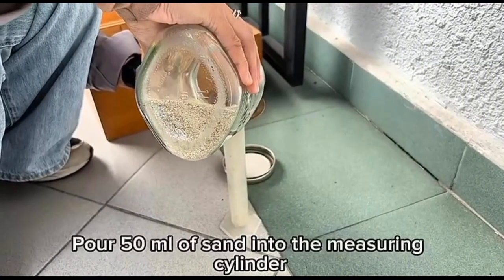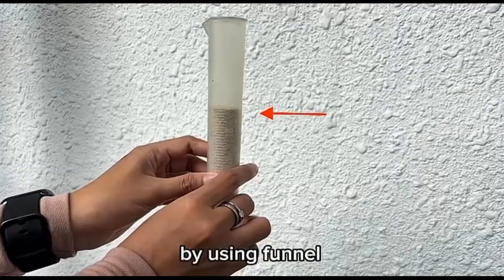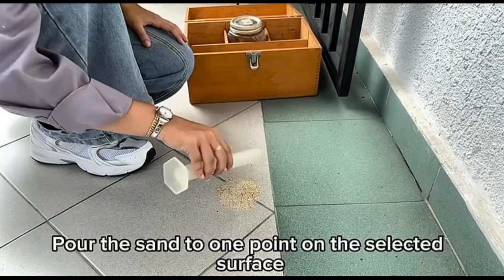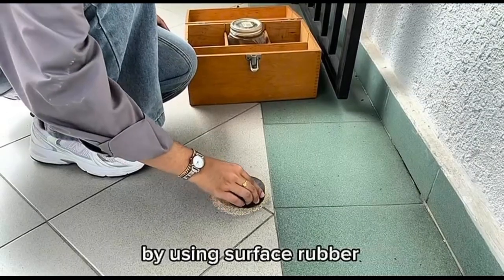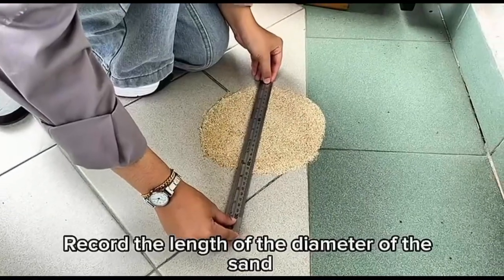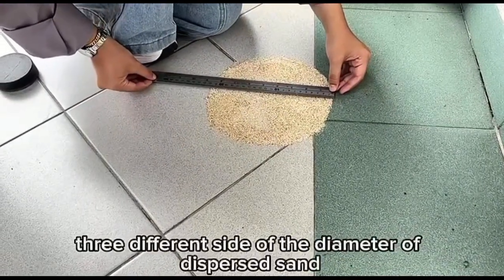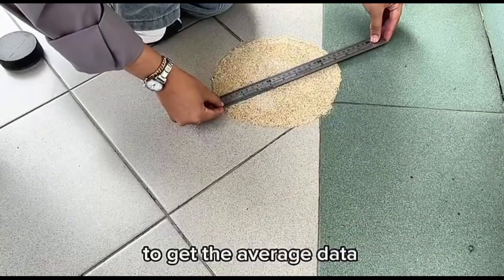Pour 50 ml of sand into the measuring cylinder by using a funnel. Pour the sand to one point on the selected surface. Disperse it in a circular motion by using a surface rubber. Record the length of the diameter of the dispersed sand and take 3 different sides of the diameter to get the average data.